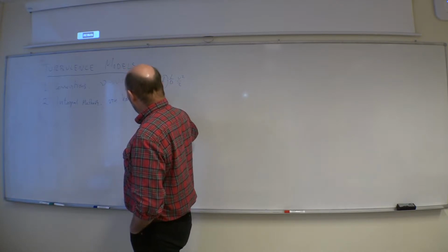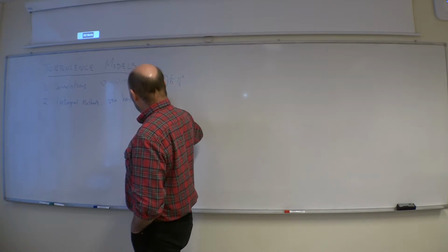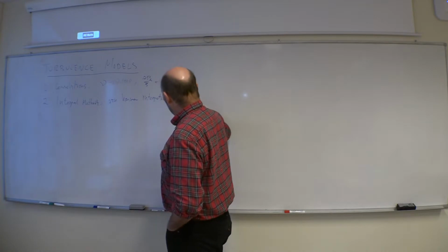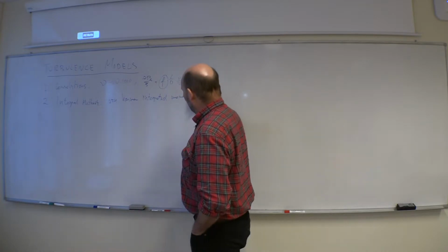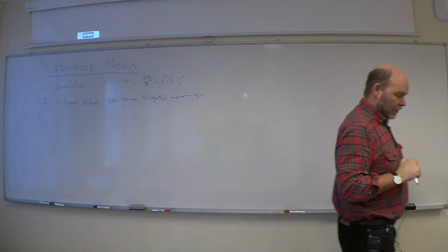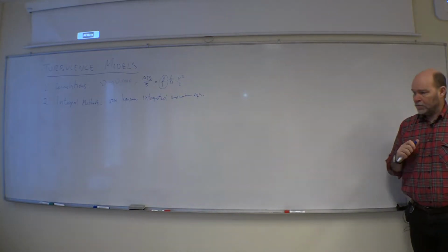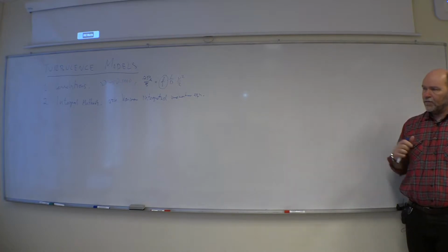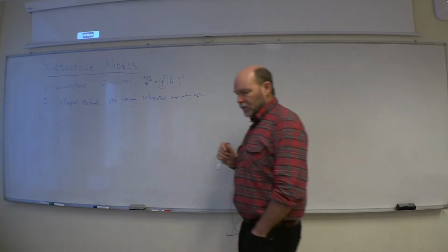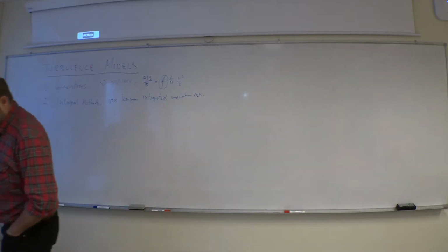He has an integrated momentum equation. You have some theory from boundary layer. You can integrate up some similarity solutions, finding the skin friction based on some integral formulation of your equations.